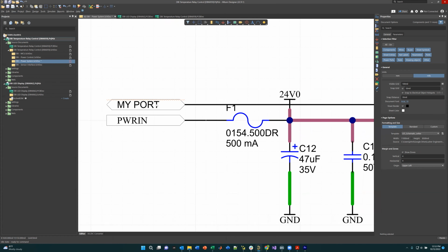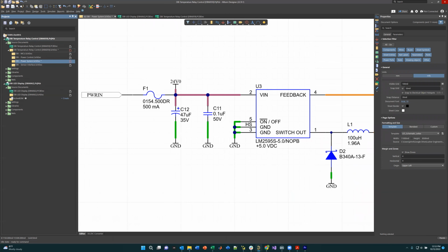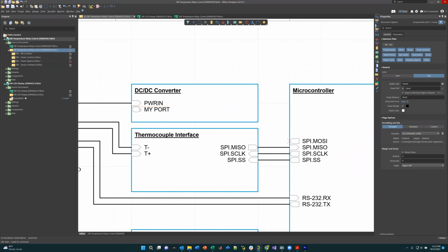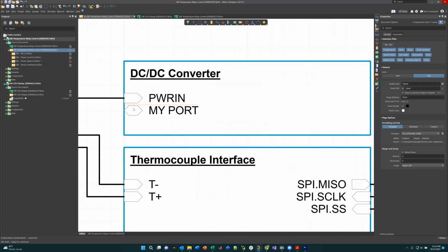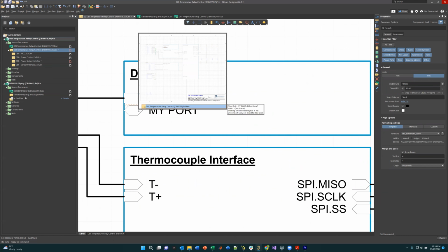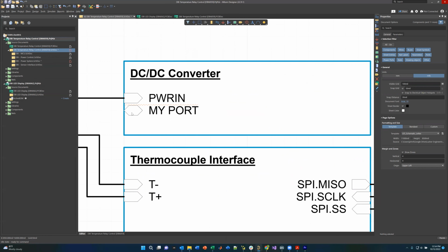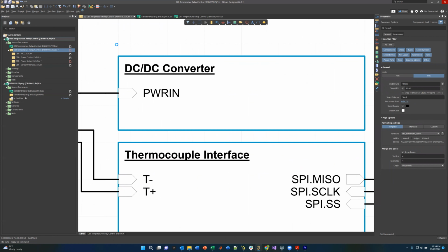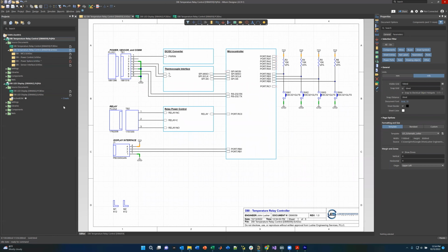So it's kind of tracking your inputs, outputs, and things like that. So obviously I don't need that here, so I'm going to go ahead and get rid of it. Notice the squiggle now appears here because I'm saying that there's a port pin or a port to this sheet that doesn't exist. So we just come and hit delete. I hope this makes sense to you. All right, so that is one of the first sheets.